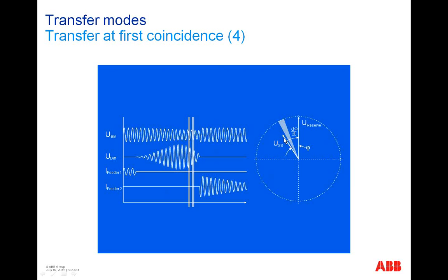the device calculates exactly the speed of this phase angle, which is going around the standby voltage. And the device knows exactly, for example here, from here to one small synchronous condition, we need 50 milliseconds. And the breaker also needs 50 milliseconds to close. Then the command to close the standby feeder breaker will be given in advance, before they once more meet the synchronous condition.